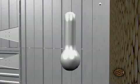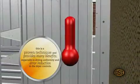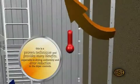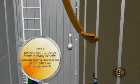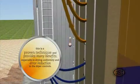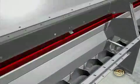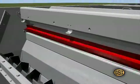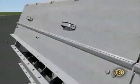In the process dryer, the drying process is controlled by controlling the temperature of the grain mass. A sensor is installed beside the drying column to measure the temperature of the air leaving the column, which advises the operator of the need to increase or reduce the unloading speed. This makes the dryer control more efficient than in conventional dryers.